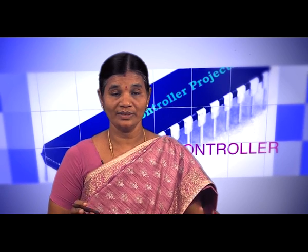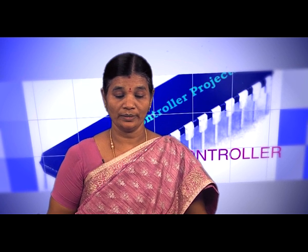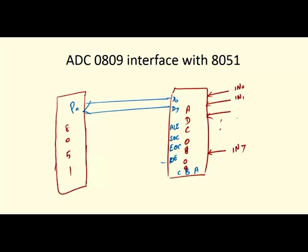Now, you have to decide which ports are to be interfaced with the 8051. Now, I assign port 0 for getting the output, the digital data. Okay. Then port 1 will be used for the remaining signals. So, port 1.0 for ALE, port 1.1 for SOC, port 1.2 for EOC, right.